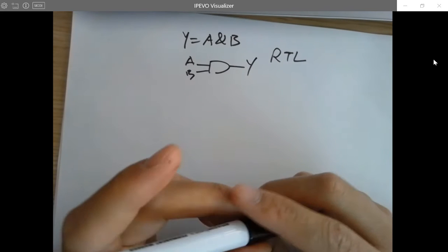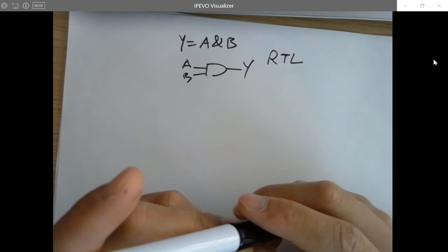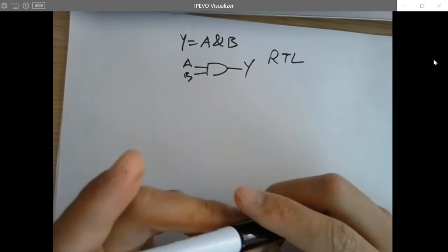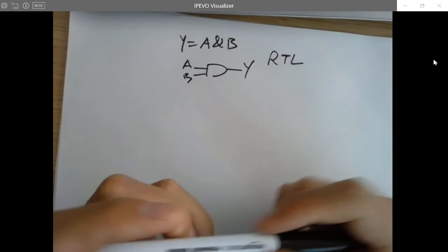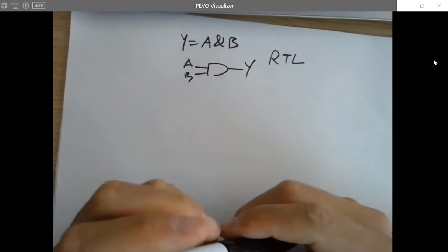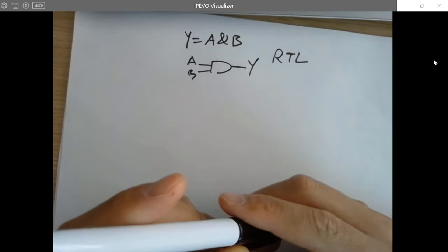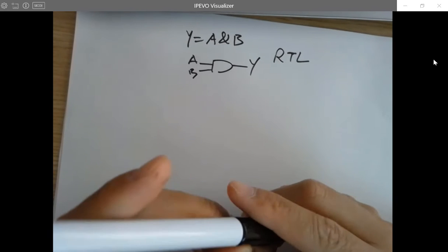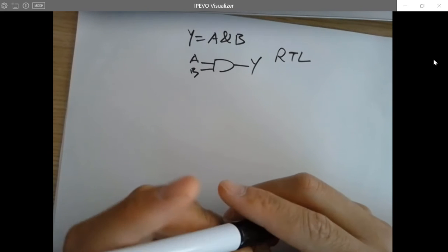So whenever you power it up, it is able to read the program from the flash through SPI to where? So you are not storing the program inside the CPU, right? Because the flash requires higher voltage to attract the electrons into the floating gate.